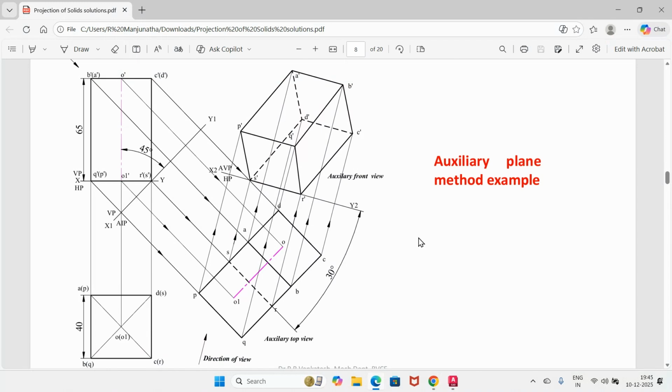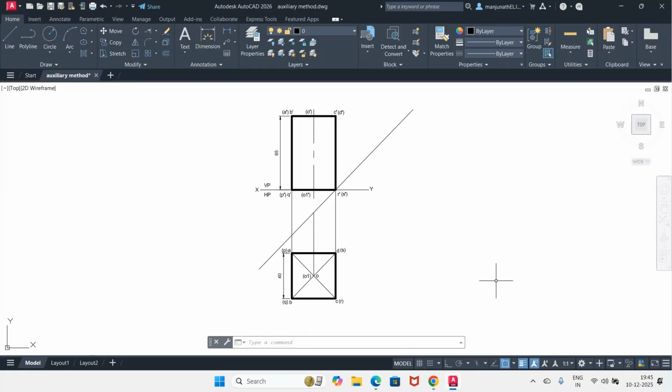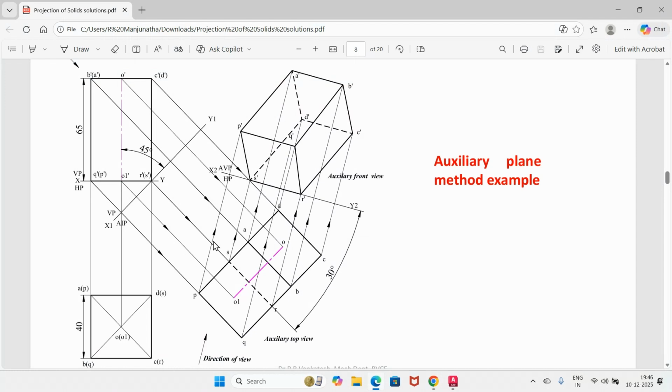So to do that, I will go for line, select endpoint to perpendicular to this line. Again, go to line, intersection to perpendicular. Again, line, take this endpoint to this perpendicular. Similarly, line, end of this to perpendicular to this. From here, perpendicular to this. Now, once you do this, this is the reason why I was telling you to take the farthest distance possible. Then after that, I need to measure the distance from these two,